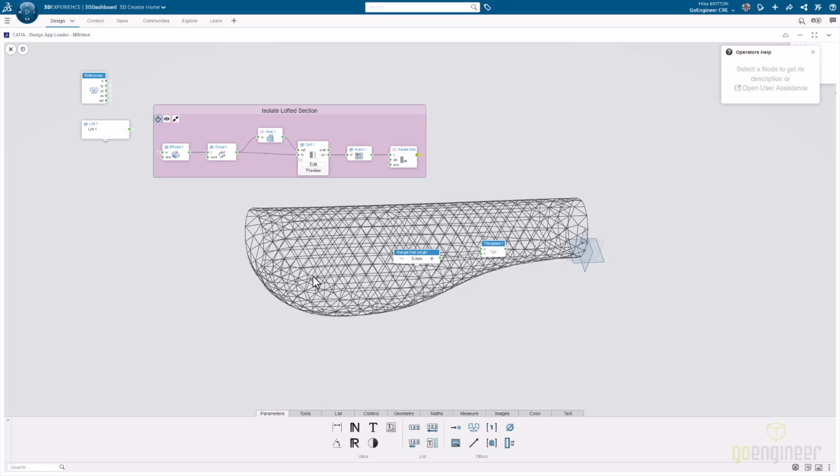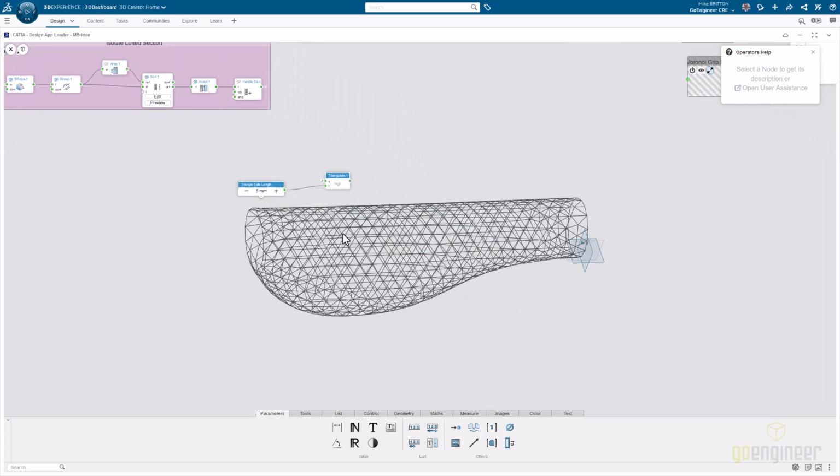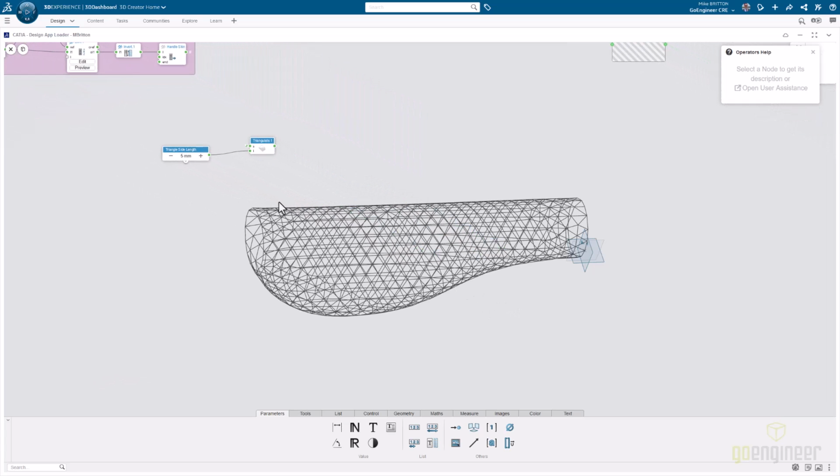And now we can see in the background that I have a triangular grid of faces that maps to the surface that we are referencing. With my 2 operators set up so far, one really with an input, I'm going to do one more thing, and I'm going to left click this triangle side length. I'm going to hit this button here to make a controller out of it. That'll be more important a little bit later, but it is something that I do want to show.